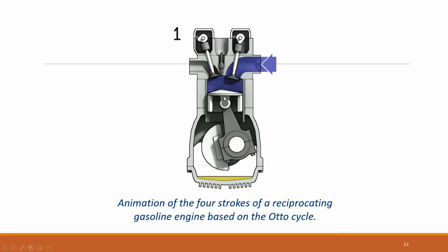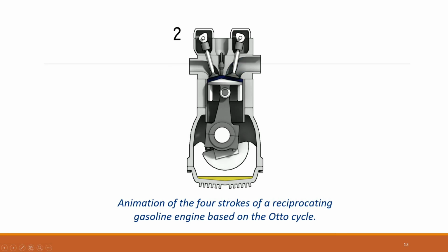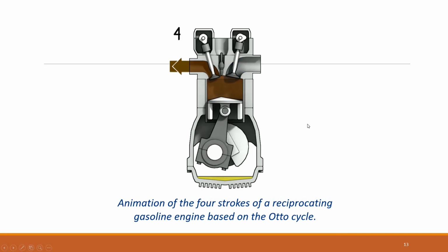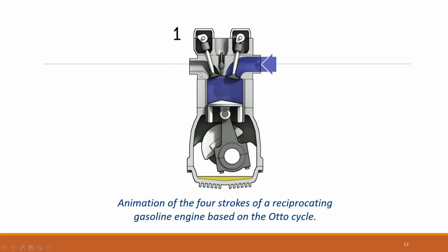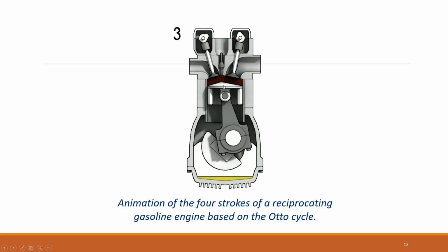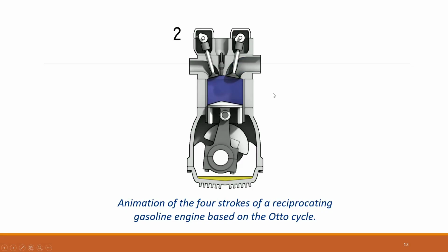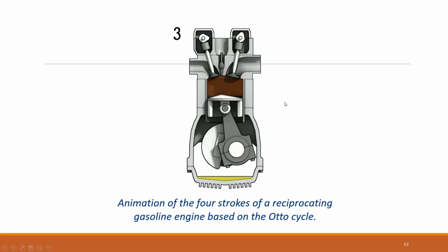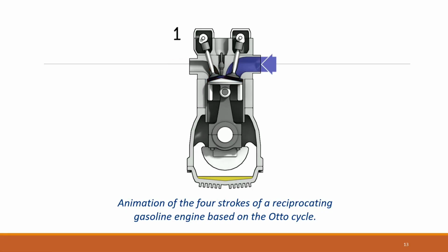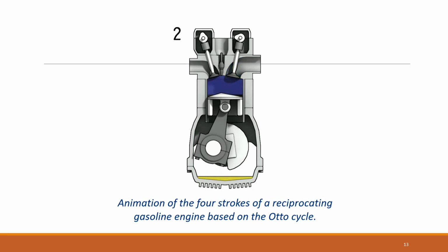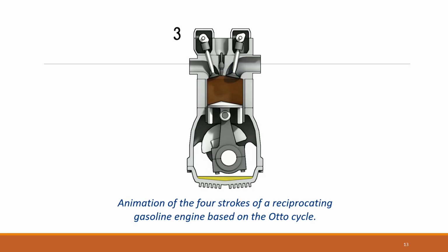A piston engine may also operate on the diesel cycle. In diesel engines, the high compression raises the temperature enough to ignite the fuel without a spark plug. Diesel engines typically offer higher thermal efficiency, lower specific fuel consumption, and in many countries, diesel fuel is less expensive than gasoline.